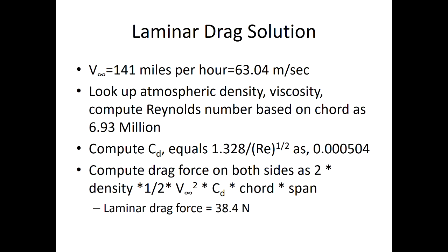So for 75 kilograms, acceleration due to gravity, 75 times 9.8, would be roughly 750 Newton. So on average, a young person with 160 pounds is exerting a force on the ground of 750 Newton. This is 1/4 of that. So it's like a 40-pound child's weight. So that's the drag force if you have a laminar flow over a Piper Cherokee wing.